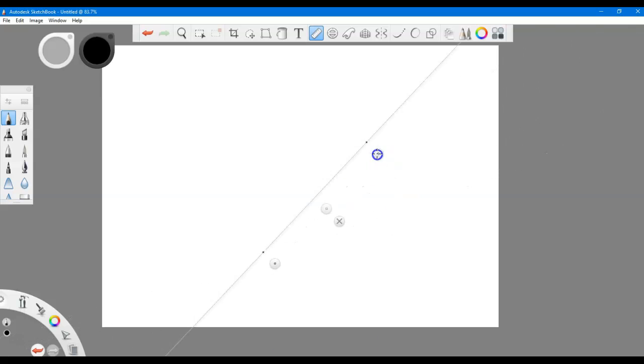The other tools that we're going to use besides the drawing is the ruler tool. It moves up and down, left and right, twist, turn, all that sort of stuff. Pay attention to the bottom. A light blue box turns up, and they represent your X and your Y axes. What we need to do is pull the ruler into the bottom corner and set it at 0, 0.